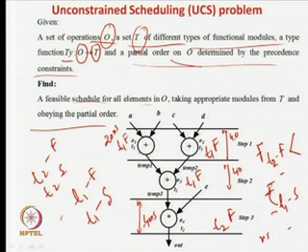So, even by using a fast adder, I am not getting any gain. I am getting the result in 20 nanoseconds, but I still have to wait for 40 nanoseconds, because everything is decided by the slowest element among all the operations. That is T2, or operation 04, the slowest one. It is taking 40 nanoseconds. Even with the fastest one I have for type 2, it is 40 nanoseconds. So, all the time steps are 40 nanoseconds.